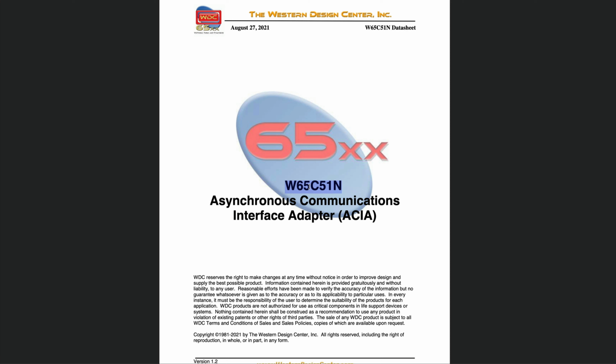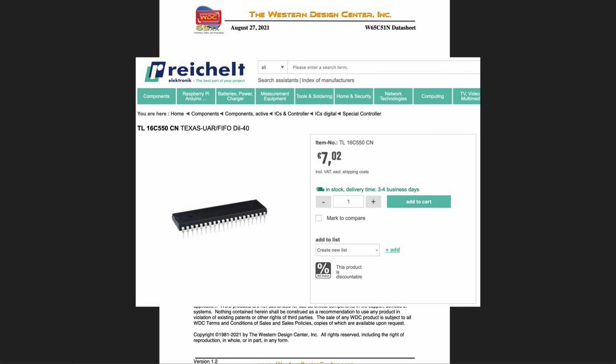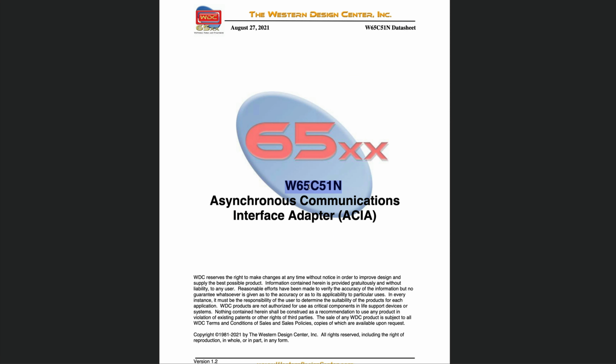I felt it was still an interesting device to talk about for didactic purposes, as it's quite simple and it's been designed by the same company that designs the CPU, and so it's great to work together. If you're starting a new project, I would recommend you maybe look at something like the 16C550, which is a much better modern UART that you can replace this with. Okay, so with this disclaimer out of the way, let's see what this device is all about.